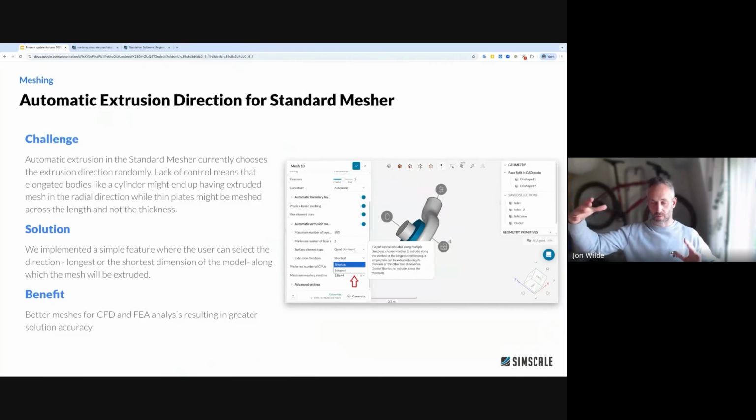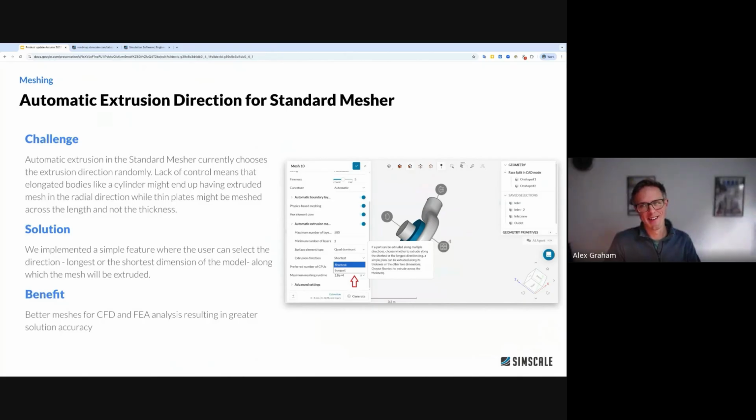So the pressure outlet is normally higher, and you normally can't assign a flow rate at the inlet. You normally have to have a pressure, which means you need a long pipe for the flow to be fully developed. Then you want to extrude the mesh in that pipe. So really what this image should show are two pipes coming from the inlet and the outlet. That would be perfect. Then it would make the discussion much easier.